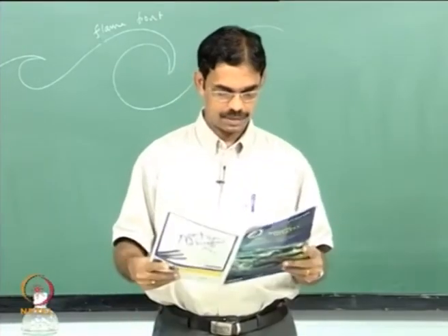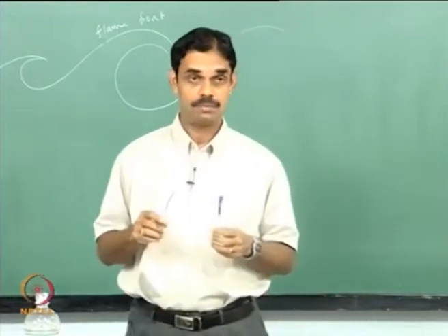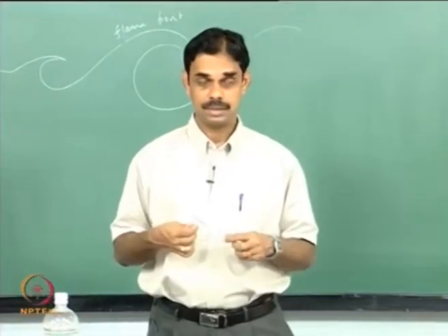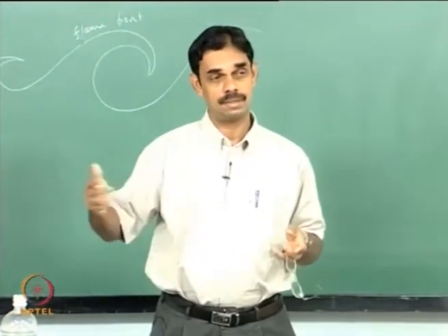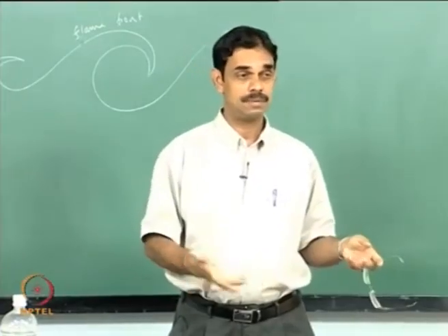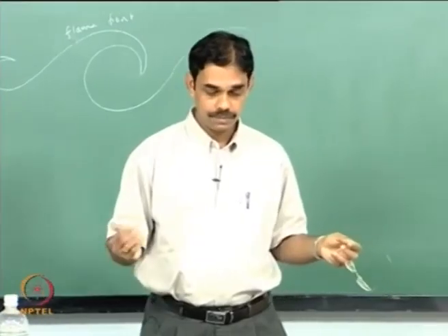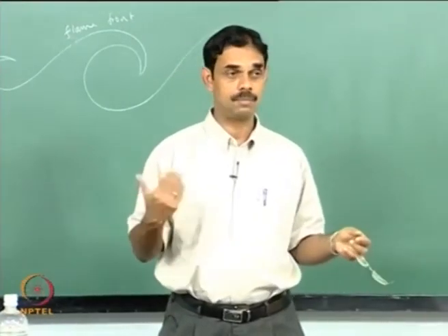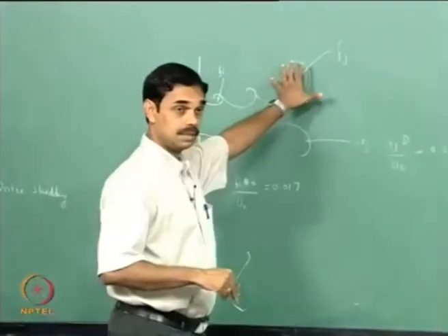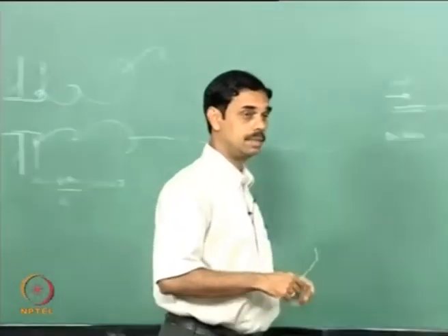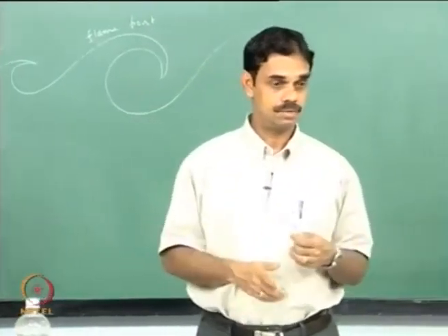Now the development of large scale coherent structures depends on the relationship between the acoustic velocity and the flow instability frequency. So if the acoustic frequency is very far away from the flow instability frequency, then there would be hardly any interaction. But if you are exciting at the preferred mode frequency, that is the frequency that is here, there is a good chance that you can make the jet very coherent, and you can have very large amplitude fluctuations.